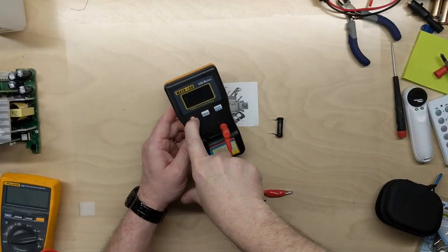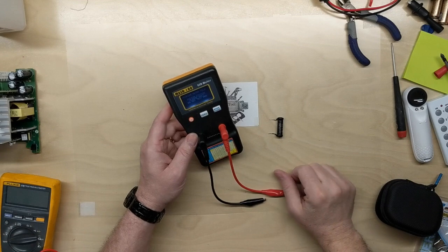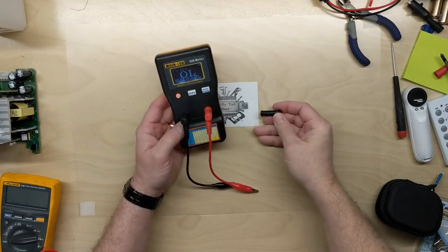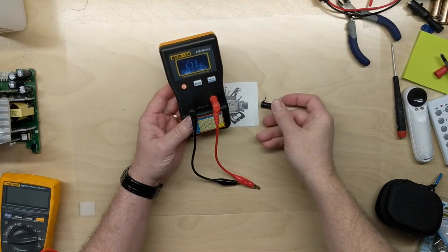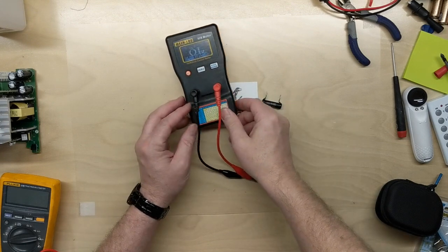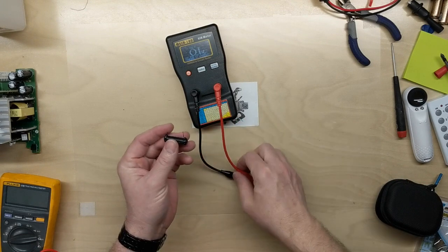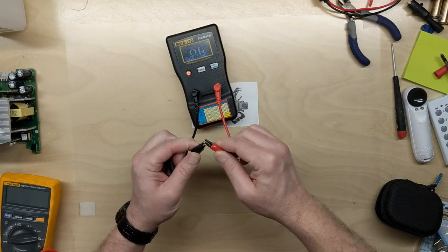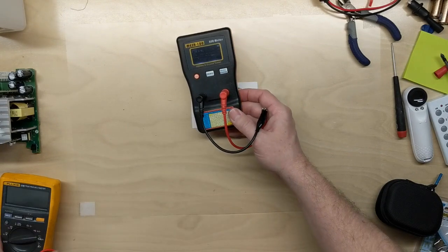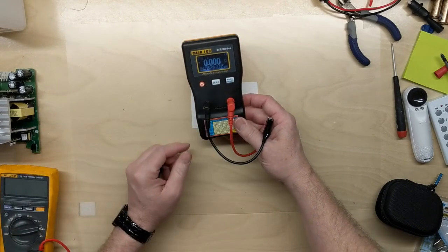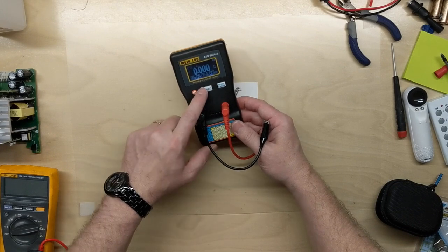I should also mention that something like this ESR meter is a really good way to check something with more precision and something that's low ohms. Because if you are getting down to something where you need precision, you need to buy a precision resistor. And of course, a regular meter, even if it does have relative mode, won't get down quite as low as these. You can zero them out.